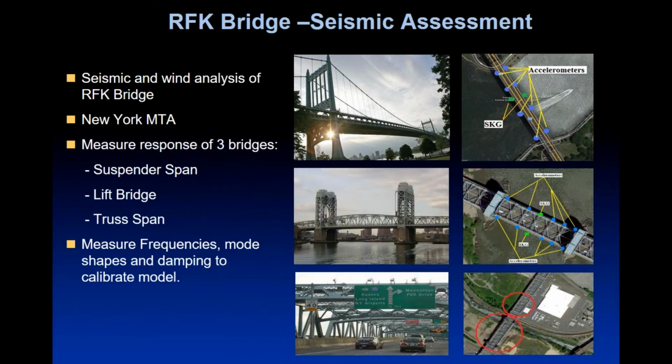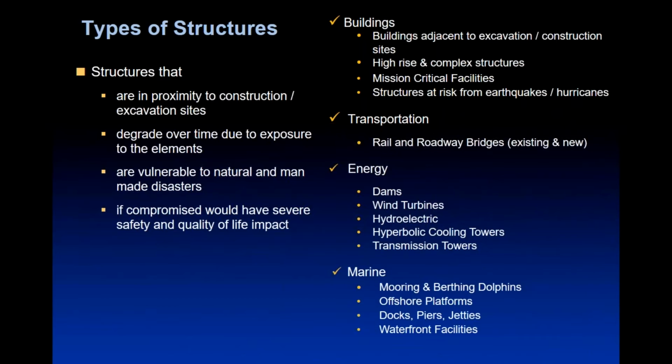1 cycle every 10 seconds. Now, it's difficult to measure at such a low frequency, but we've done it. We've retrieved not just the frequency, the period, from that structure, but also the damping and the interaction of the structure with the wind, so that we avoid the problem of the Tacoma Narrows type effect.